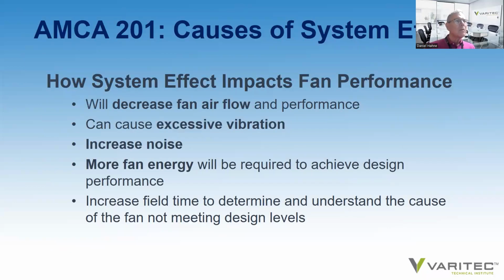Well, first of all, let's look at how system effect impacts fan performance. It will decrease the amount of flow the fan can otherwise provide when it is not taken into design consideration, can cause excessive vibration, increased noise levels of the fan, can result in greater fan energy consumption because to overcome it, it is frequent that you increase the fan RPM, providing the motor horsepower is available to do that to a certain point.